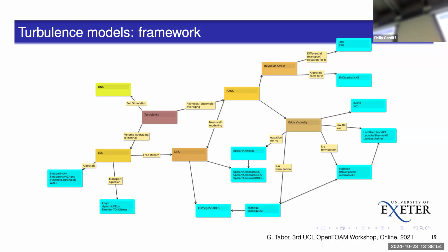So there's this continuum. And then DES is a combination of LES and RANS, so you're kind of combining bits from here. So that's the main takeaway: DNS, most expensive, most accurate; RANS, least expensive, least accurate; LES, somewhere in between.